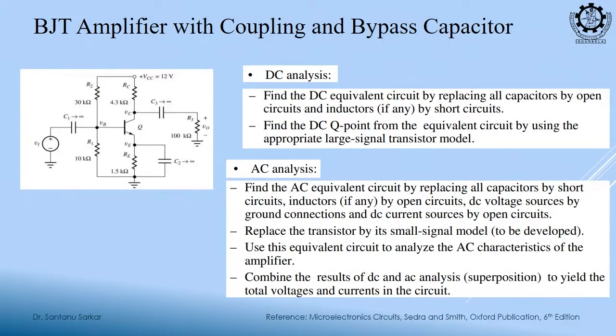Good morning. We will continue our discussion on the bipolar junction transistor. In the last class we saw what the complete biasing circuit for a common emitter amplifier should be. To DC bias this, we need a bias potential VBB. Our objective is to minimize the number of DC sources, if possible to a single supply source only. So, from this VCC supply source we will generate this VBB.